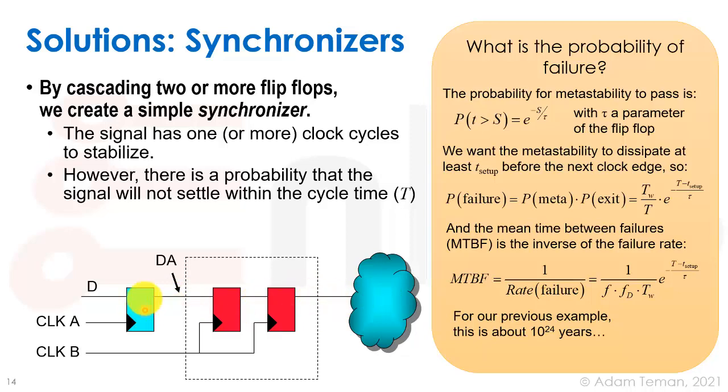So we have to build our logic that talks between the flip-flop over here and the logic down here to the point where it's not going to be sensitive to that one cycle that may be lost or may not be lost. But the synchronizer is the main way that we can solve metastability problems at a clock domain crossing, as long as our design is built to enable such a non-clear value that's going to be going downstream in a certain clock cycle. Okay. That being said, there are other ways to solve clock domain crossing, such as using FIFOs. But that is one thing.